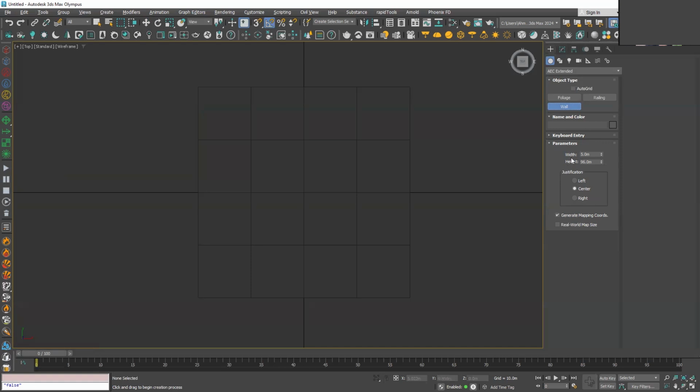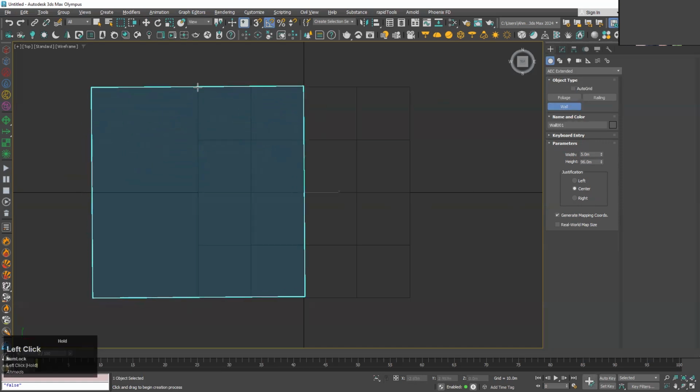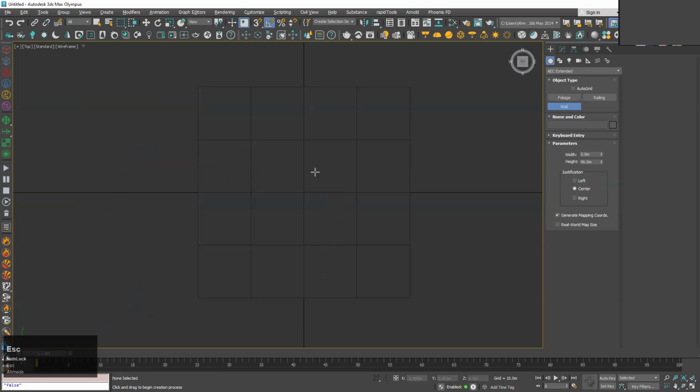But obviously, in terms of 3D, we are a little more concerned with the three axes, three dimensions, but we don't see any length over here. So the length is basically this floor plan's dimension. If I just click and drag, the length parameter is going to cover this area or the dimensions we have for the floor. So let's start our wall.